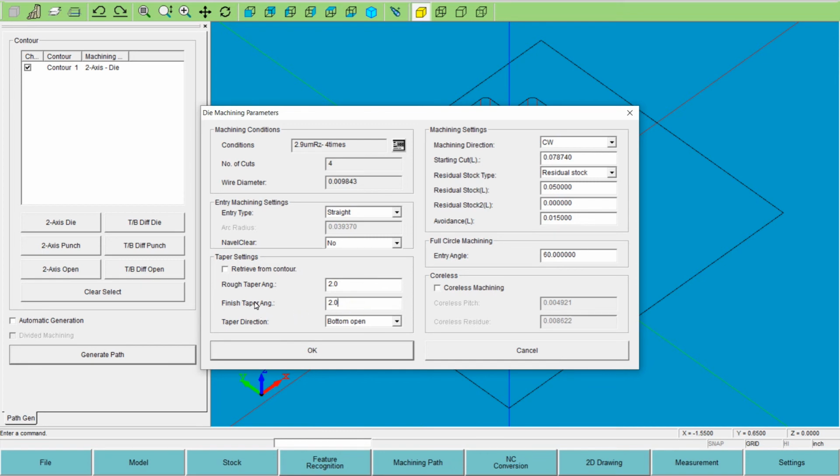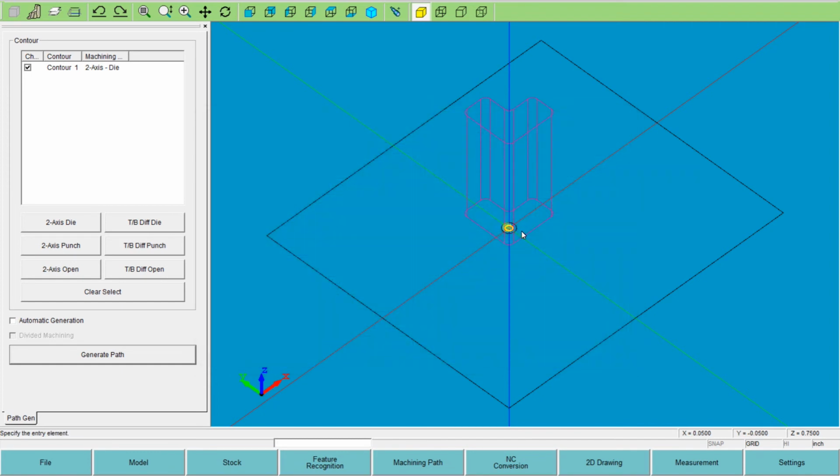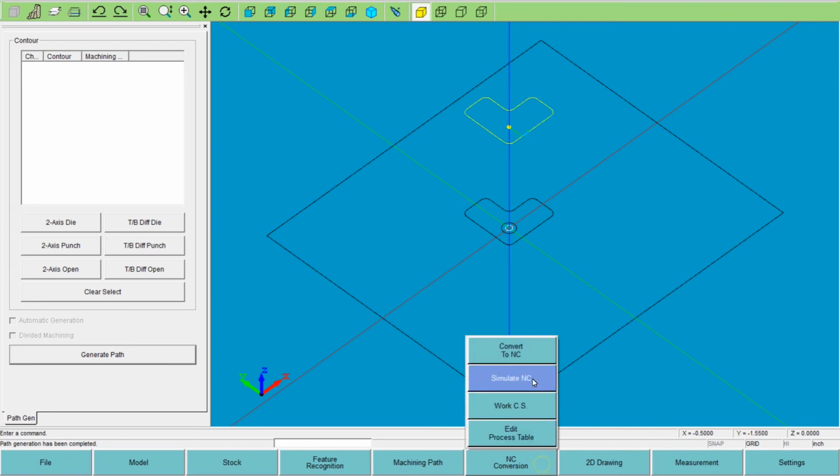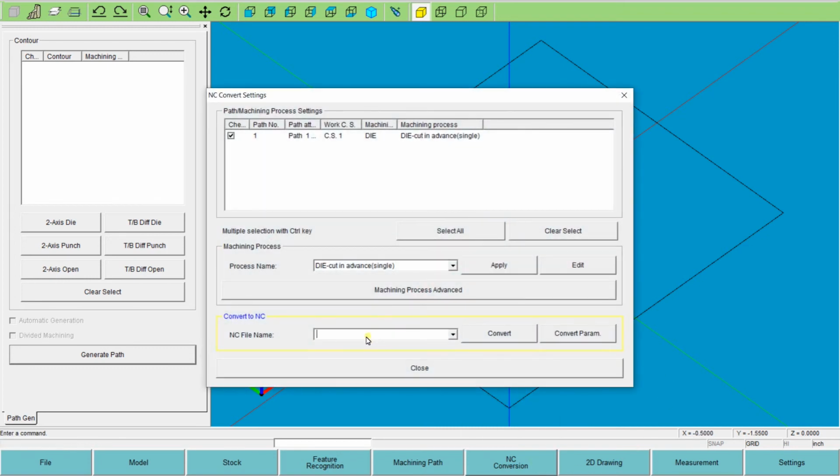What finish taper angle allows you to do is zero out the taper so you can put a land on the part. So in this example, I'm programming straight to the top with the taper. I didn't leave any stock up there for a land. So we're going to leave the angles set the same for both. And you just make our program. Okay, and then you can graphic draw that, generate the NC code. Let's say taper 2.